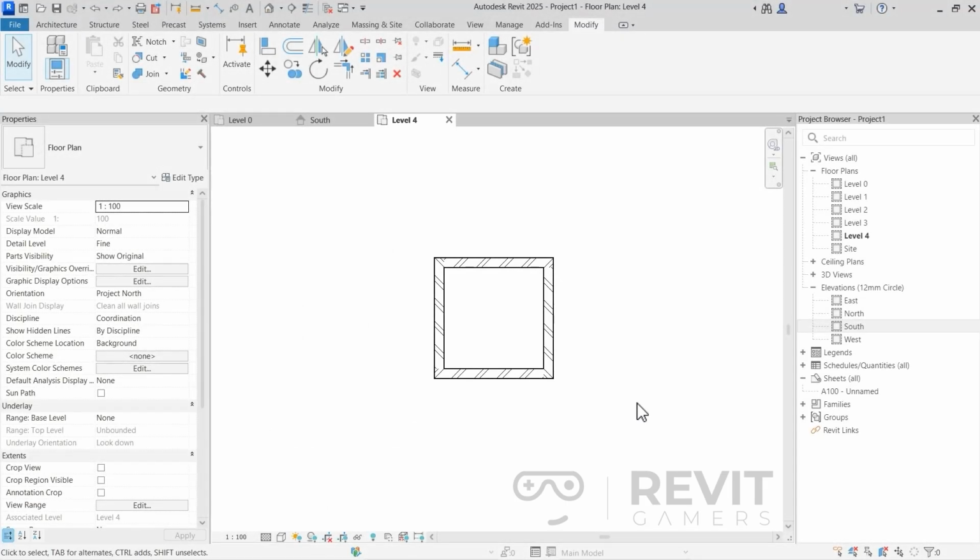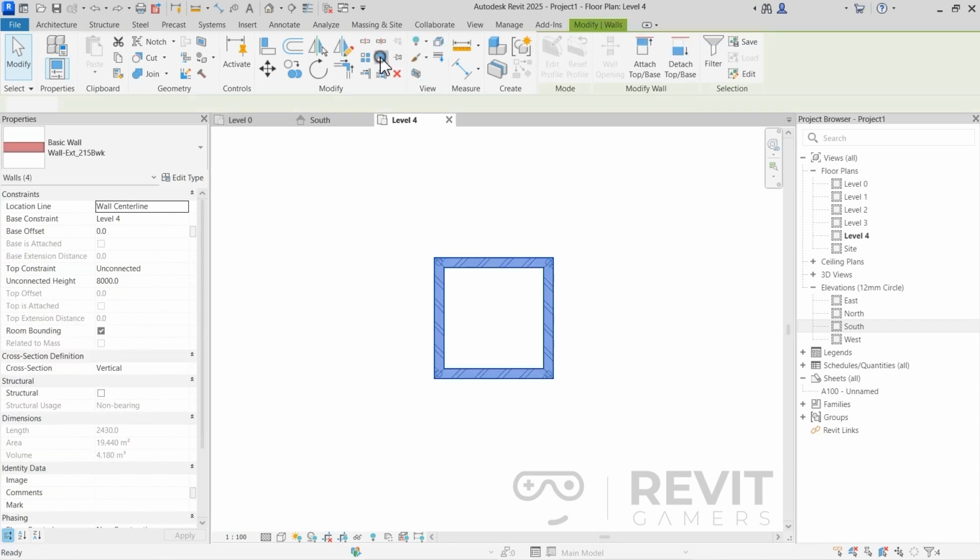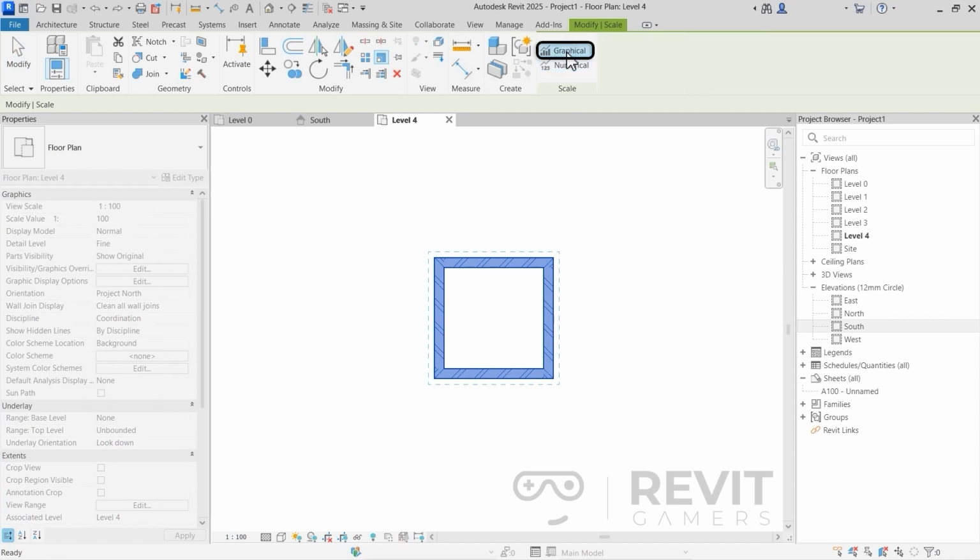If the scale amount is uncertain, select Graphical and specify the scale value manually with 3 clicks. To do so, select the object, select the Scale tool, have Graphical selected, and then specify the base point with your first click. With your second click, specify another corner of the object, and finally, make a third click to determine how large or small you want the object to become.